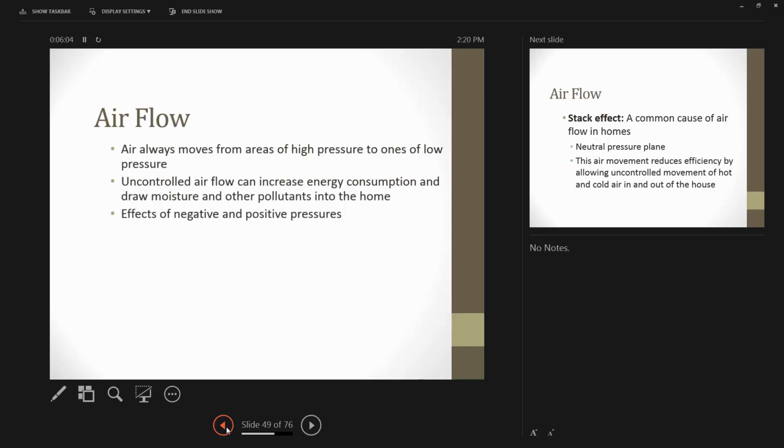And whether it's coming in from the outside or whether it's going out from the inside, that moisture, if it gets into the wall cavity and reaches a certain temperature, has the potential to condense. So as we get buildings tighter and tighter and tighter, which is the number one thing that we've been doing in energy efficiency over the last couple decades, we do cut down on the heat loss, we do cut down on the amount of airflow inside to out, but we also trap a lot of that air. And with that air that we trap, we have moisture vapor with it.